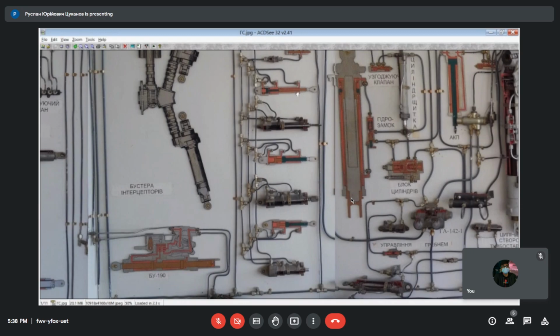So by pairs, one pair for inboard, one pair for midboard, and this pair for outboard. All the flaps are interconnected mechanically, but each of them has its own actuator, and this interconnection link can be destroyed by some damage, and they can be controlled independently.